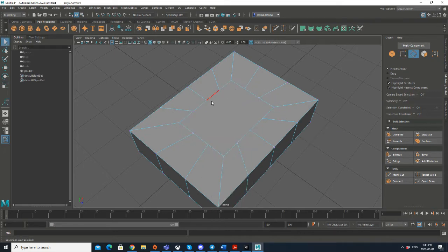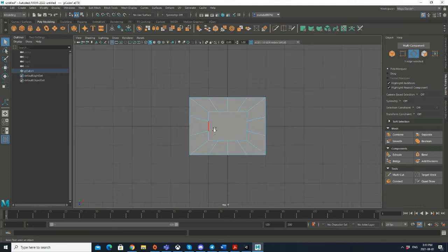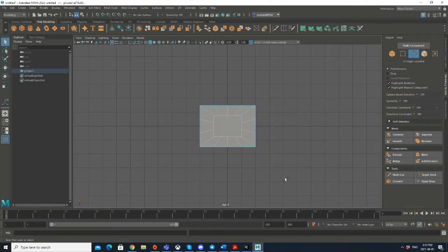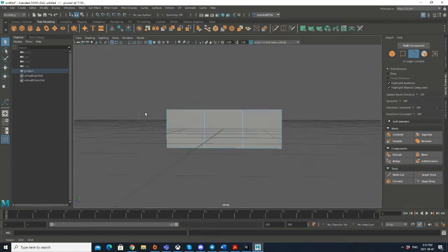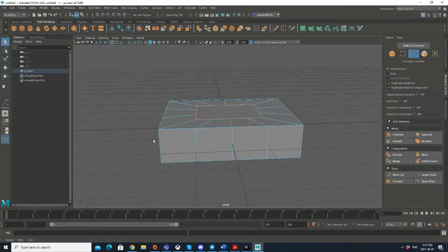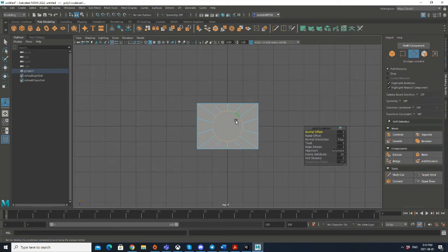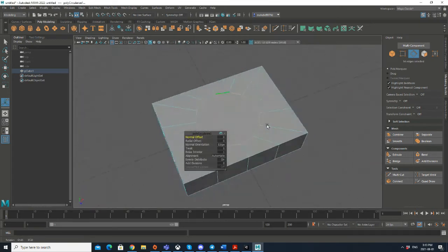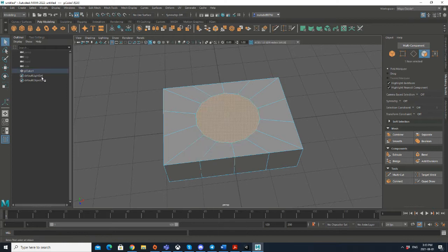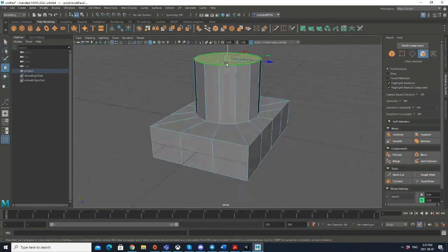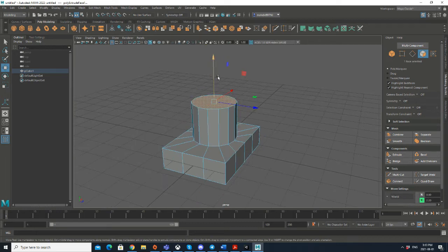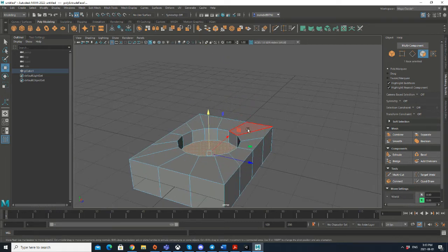Okay, and then what you can do is select these edges, and then deselect the ones you don't want. Obviously you should check whether you have selected unwanted ones from the bottom, and then go to this mode, use this button, circularize, and you will see a nicely shaped circle that you can use for extruding upward or downward, or whatever you want.